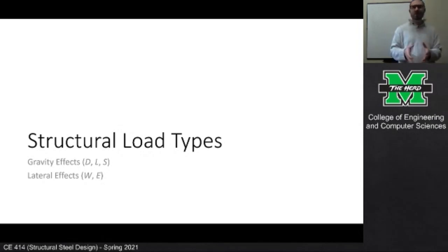When you're using unshored construction, in other words, no temporary supports, no temporary formwork or whatnot, the structural beams themselves would probably have to be bigger because they have to support the wet concrete by themselves. So the in-service structure, once it's complete, will probably be bigger than if you used shoring. But shoring takes time, effort and energy to put together. Shoring doesn't just magically show up on the construction site. Somebody has to put that together.